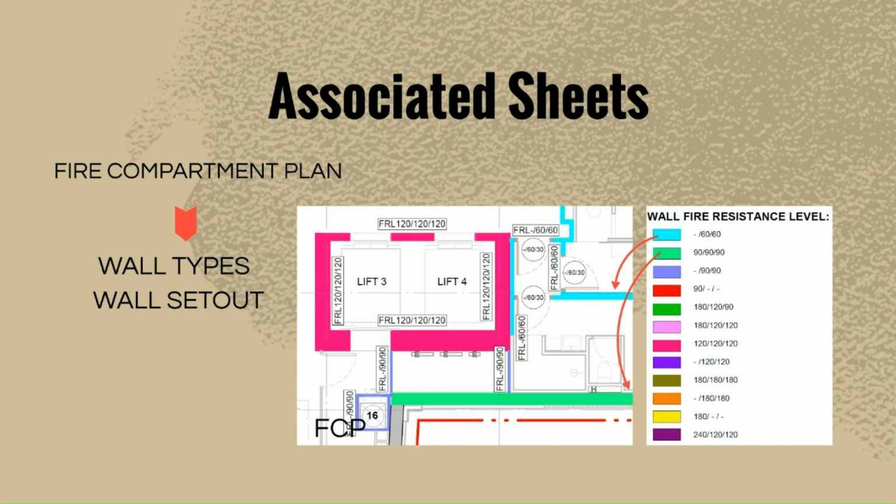All those things are important because when you are going to make a decision about the wall types and wall compartment, the overall fire rating should be matched with this plan. That's why you need to select the material that directs you to this level of fire resistance. That happens in acoustic matters and also all other factors impacting walls as well.